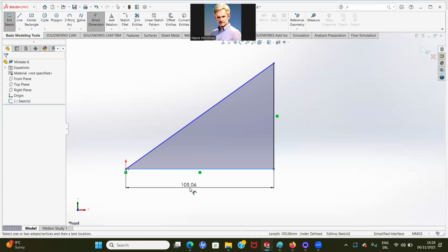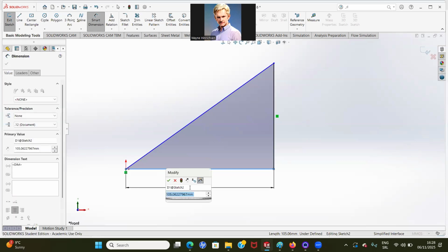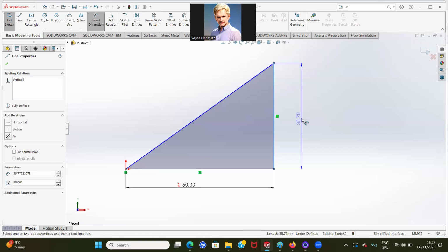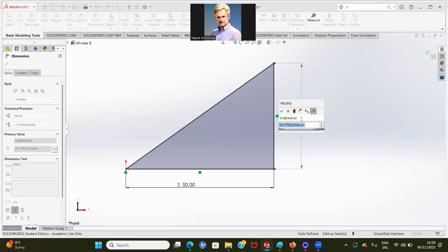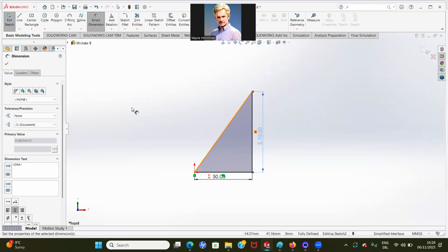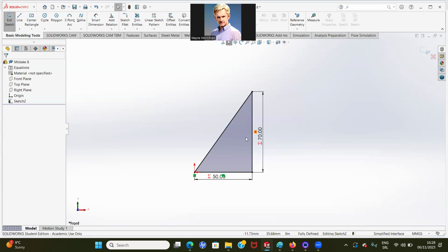So we have to say, okay, this dimension will be A. So go here, equals global variable, and I can choose here A, B, or C. I'm going to go with A. This one here, I'm going to put it as equal B, right? And now what happens? If I change one dimension here, automatically other dimensions will change.